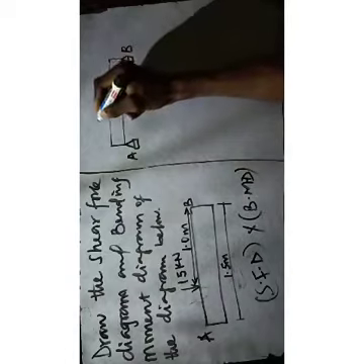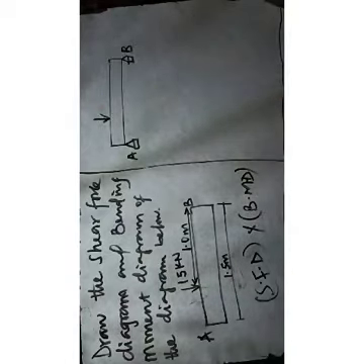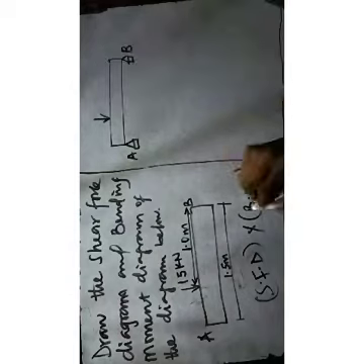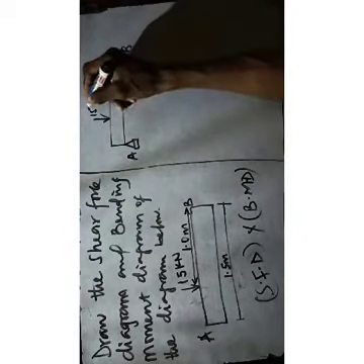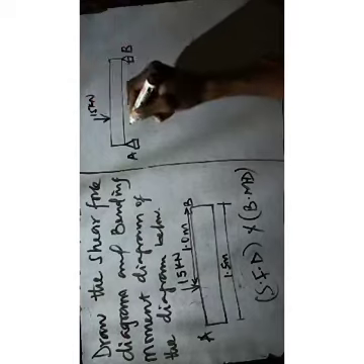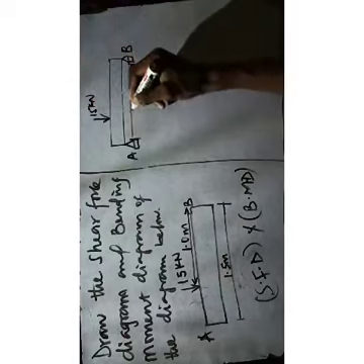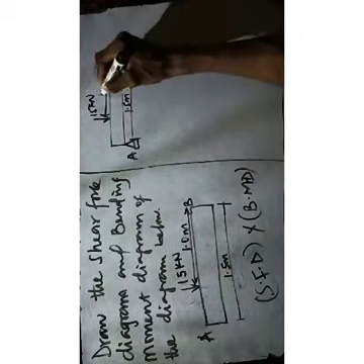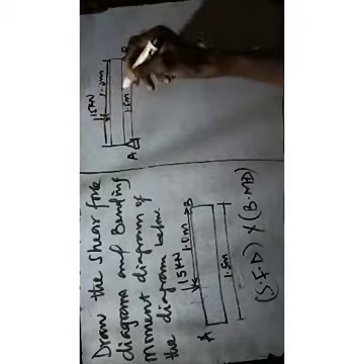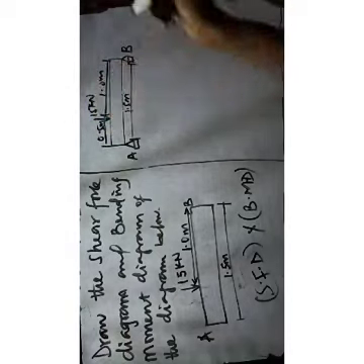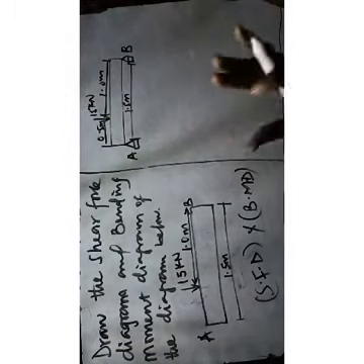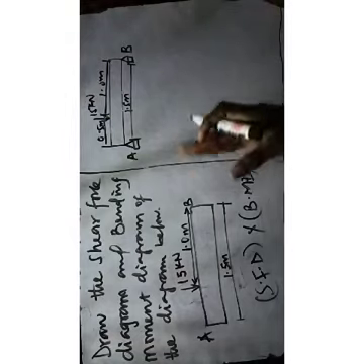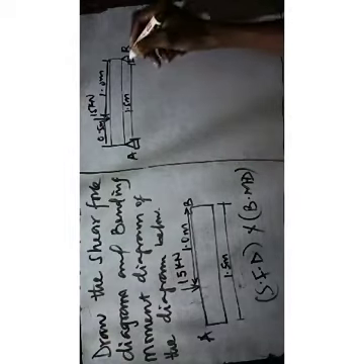Then the force acting on it is in this diagram here. This is a force of 15 kilonewton. It's important you draw a diagram and know the total distance. This is 1.5 meter. If here is 1 meter, what will be here? 1.5 minus 1, that will be 0.5 meter. Okay, that is the first stage. The next thing you do is you take bending moments, and we call this a point load.